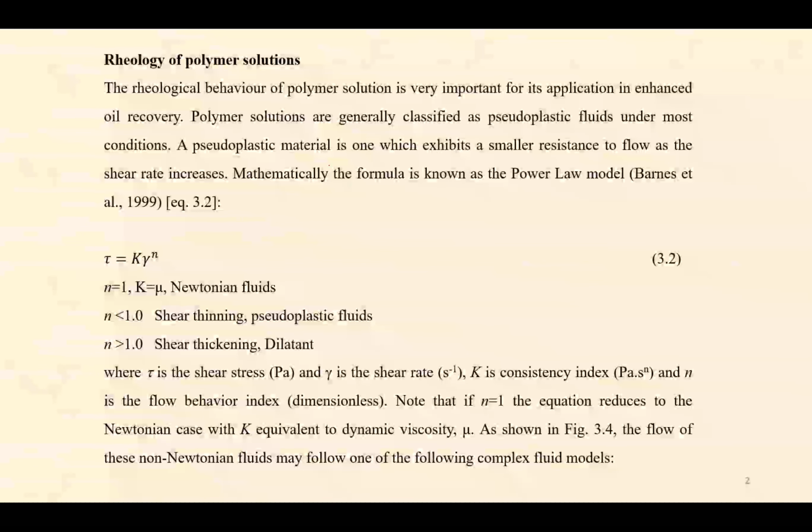But the viscosity should not be very high, so that injection may not be a problem. If we inject at high pressure, there may be formation damage, and that is not expected.